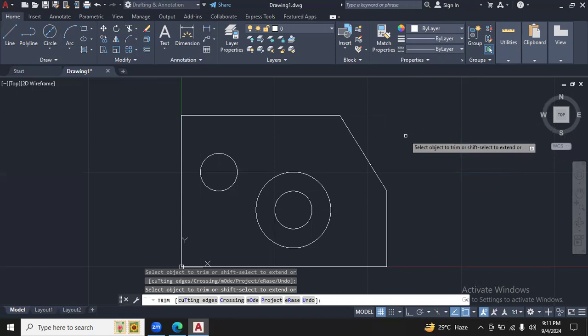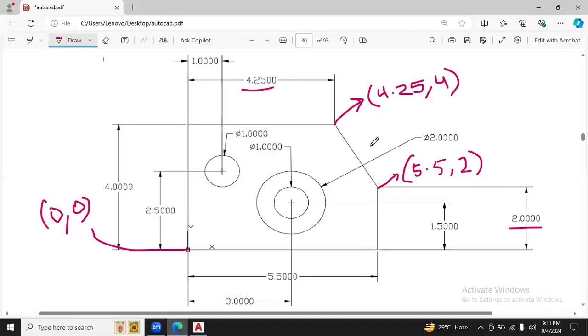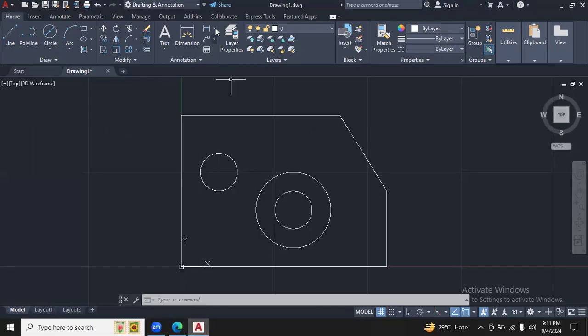That is very much user friendly, and you will need this command in all of your upcoming videos, basically in all your lectures. So, what is the last step? Last step is to mention all the dimensions. So, just go for them. First is the linear one. So, place your cursor again until you find the endpoint appearing on your screen. Just click it now. Next point for the line. Again, the endpoint is here.